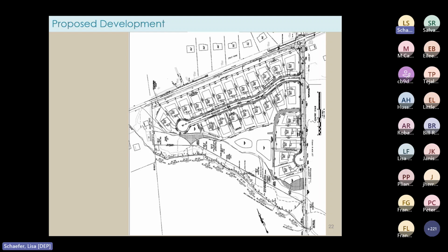Now, I started checking the coverages, and the homes are about 0.35 acres each on average, so that should come to 8.75 acres. The proposed roadways are 28 feet in width, so by my estimate, roughly 70,000 square feet or 1.6 acres of new motor vehicle surface are proposed. Additionally, the existing portions of the roadway along the east side of the property will be newly collected where no collection system existed before. So it all counts towards a net increase in motor vehicle surface. These totals clearly exceeded the threshold for major development.